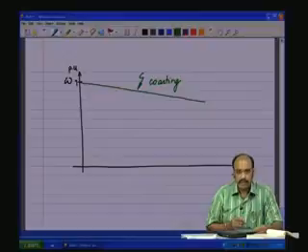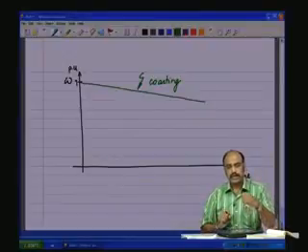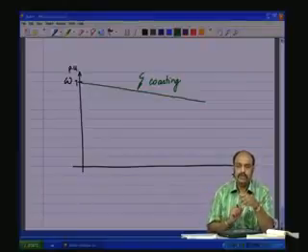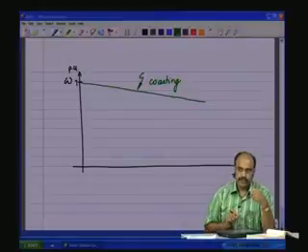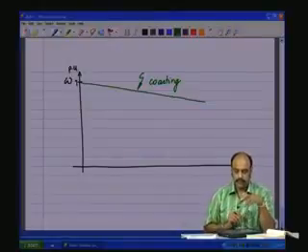Mechanical braking and dynamic braking are similar, only that in the mechanical braking you are applying a mechanical brake by applying friction onto the shaft by means of brake shoes. That is, you are creating a mechanical friction where the energy is lost as heat due to the friction.